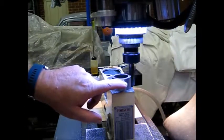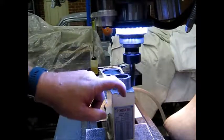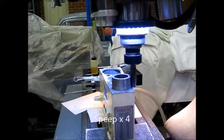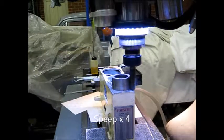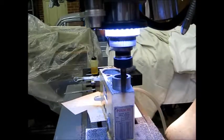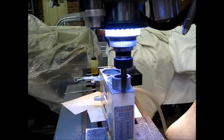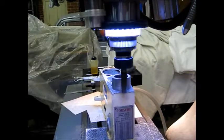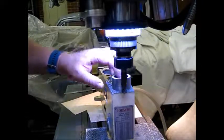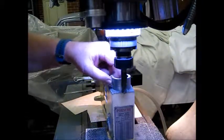I will put an instruction to move the tool 5mm away from the job when we get here. So we're coming to the finish and we're moving away so that we can shut down. I'm turning the spindle off manually, and I think we've achieved what we were looking for there in now a parallel wall all the way around